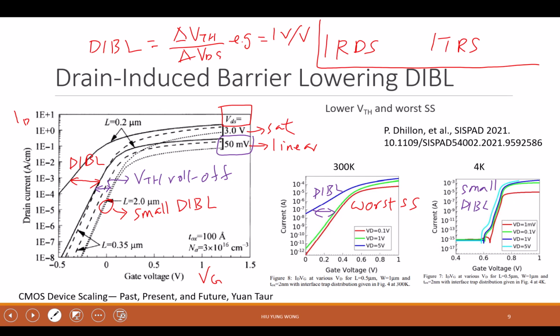Okay. Yeah. And you would expect the curve in that subthreshold region to go in a straight line with the log scale on the y-axis, whereas one has a big bunch of kinks. So how does that fit with the subthreshold equation of the transistor? Yeah. So this is completely because of this paper we did. We tried to model the subthreshold slope using traps. And when we do the traps, it's very difficult to make it smooth. So we do not match the experiments well. What we did is just on average, it matched the slope of the experiment, but we did not try to fix this corner. So this is just because of the model.